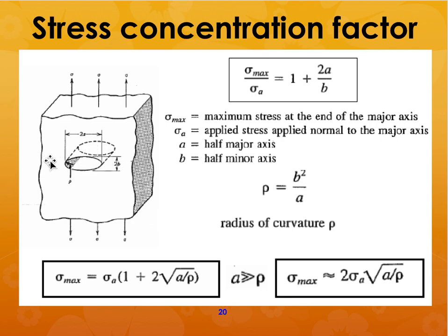So the shape of these holes is going to control how much stress is applied at these edges and how that is going to affect the failure strength of your material or your component. So if you know the hole type and size and things like that, you can actually calculate what is going to be the maximum stress in this material.